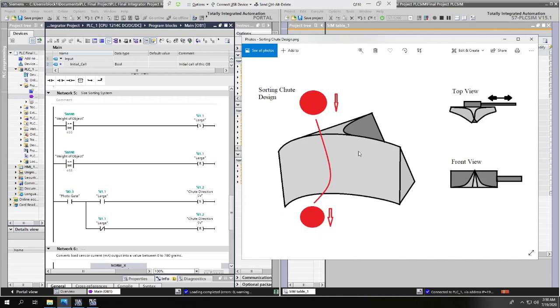And that way too, by setting the system, you don't have to change back and forth if you have 3 small objects in a row. It's less strain on the system, especially the solenoid valve extending out and going back in and out. So multiple objects in a row will result in less strain, less maintenance required on the applicator, and it's just more efficient that way.